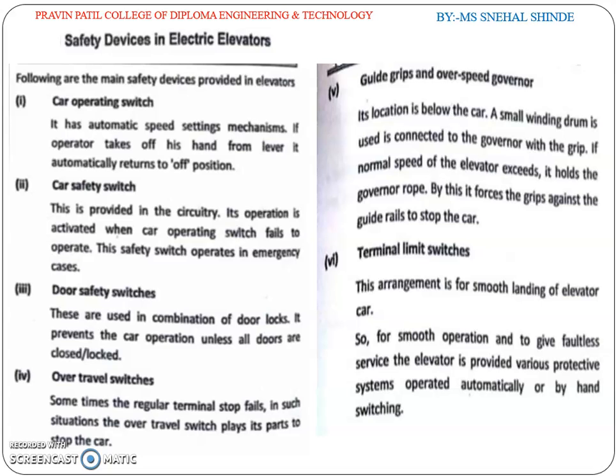They are mounted in an accessible location in the elevator machine room and usually enclosed in a metal cabinet. Circuit breaker and overload relay. Overload relays are used in order to secure protection against overloading of the elevator itself. They are normally set below the fuse rating.